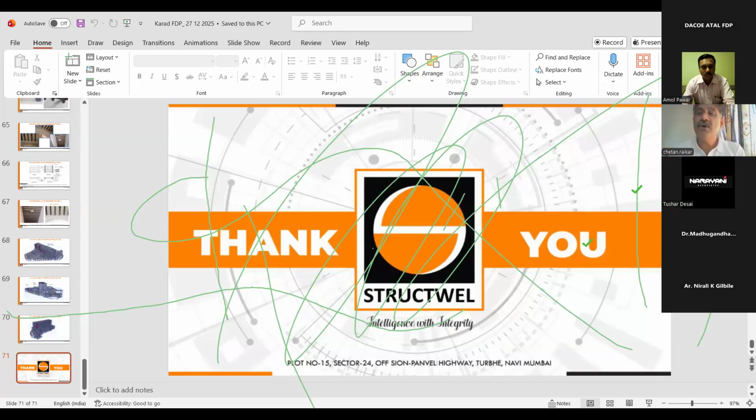Very interesting. See, just the right is the mantra of doing any repairs, whether it's heritage or otherwise. Do just the right. Now, what is just the right? If a client says, I want this structure to last for 50 years after you have restored, then just the right is understanding a material that is not going to degrade substantially in 50 years. If the client says 25 years is good enough for me, then 25 years. If the client says, I want a structure which will last only for 1 year, then leave the client. He is not worthy of being your client. No structure can be restored for less than 25 years of good quality service life. I believe that's been my principle of restoring structures. So go for just the right kind of repairs or replacement or anything.